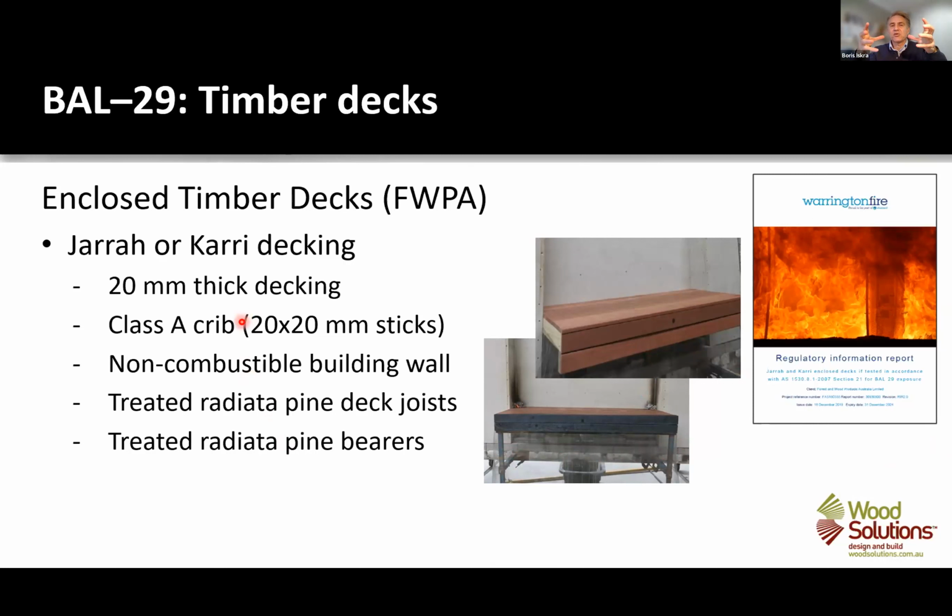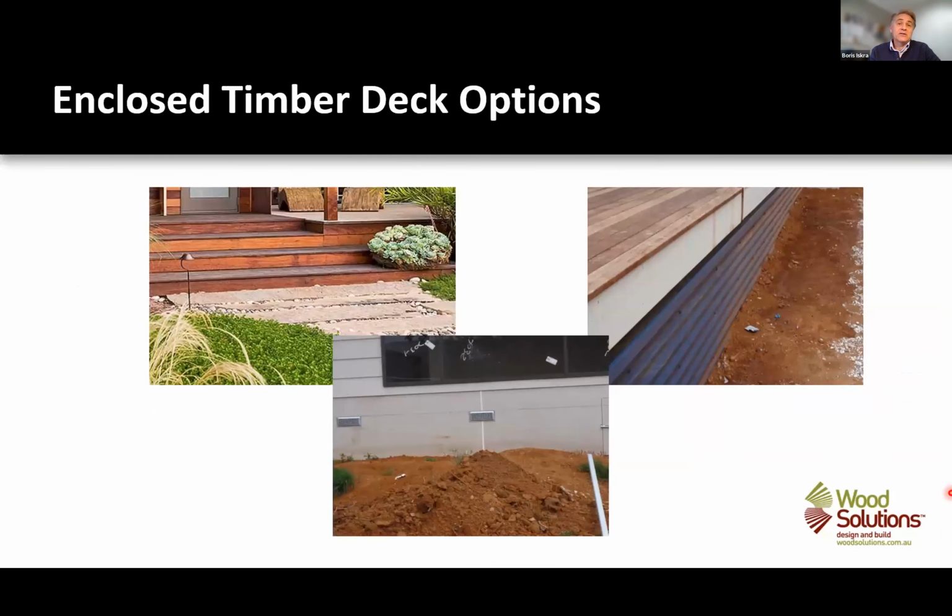So there's a timber crib that's placed in under the deck if it was an unenclosed deck. And so that's where trying to simulate where leaves and burning debris gets in underneath the deck and causes a fire from below. So the testing can be done, and you can come up with some timber solutions where they are currently not nominated in the bushfire standard. So that was for enclosed deck scenarios.